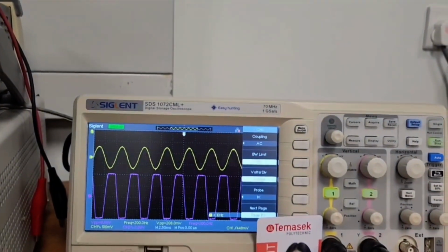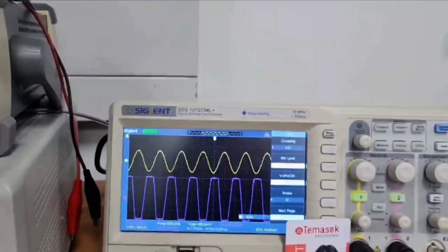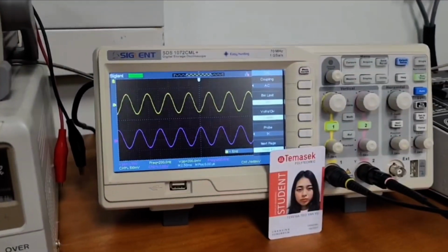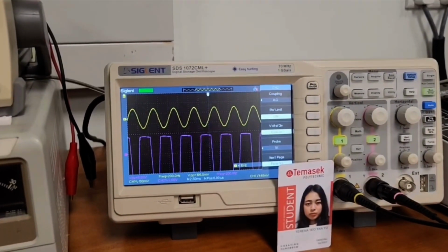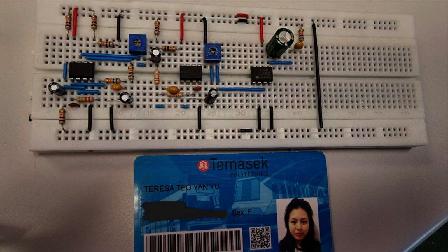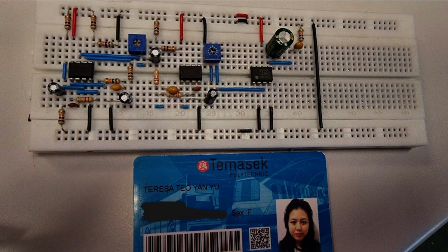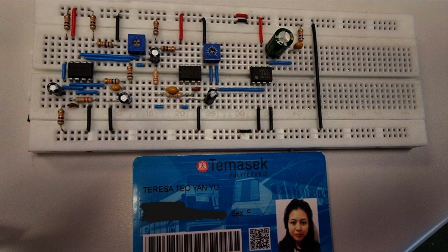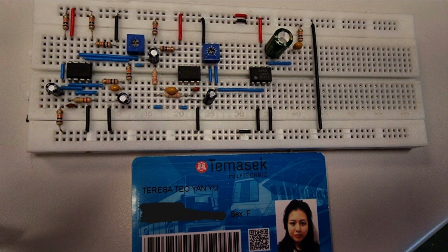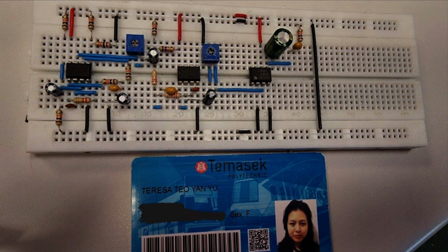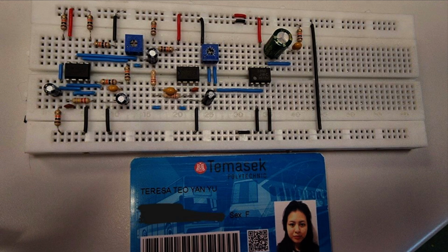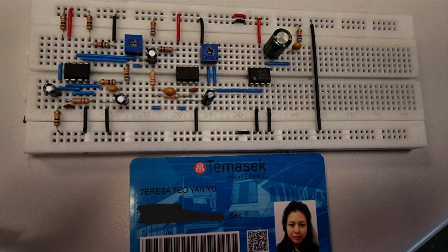As mentioned earlier, stage 2 leads to the signal being inverted amidst the signal processing, but this has no practical effects since phase inversion doesn't change how we hear sound, so there's no need to invert it back. This shows that the circuit has successfully amplified the weak input signal from the microphone to a strong enough output to drive the speaker. Overall, this confirms that each stage, the preamplifier, inverting amplifier, low-pass filter, and audio amplifier, is working correctly to process and amplify the heartbeat signal for output, and so the signal processing system